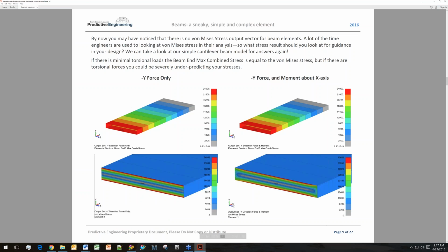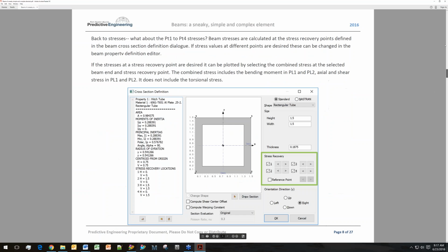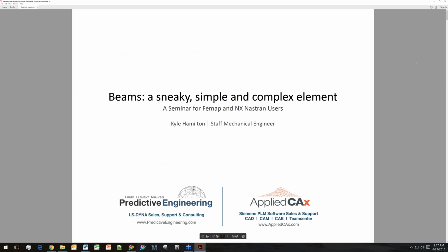One of the things that I always suggest to everyone is, if you're having questions and you're not really sure how it's working, before you incorporate these techniques into a large model with high repercussions, build a test model. You can learn so much from a 1 or 2 element model, comparing beams versus plates or solids and the way they're calculating stresses.